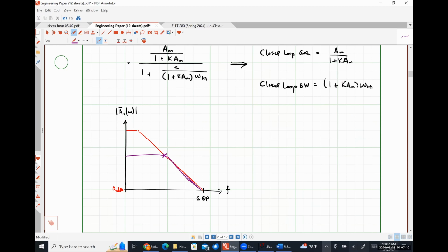We've lowered the open loop gain from the ballpark of 200,000 or so for a 741 op-amp down to something more reasonable that's just established by the ratio of the resistances that we apply. If it's an inverting amplifier, it's negative R2 over R1. If it's a non-inverting amplifier, it's 1 plus R2 over R1, and we extend our bandwidth in doing so. So now we have a more formal explanation of why bandwidth extension works.